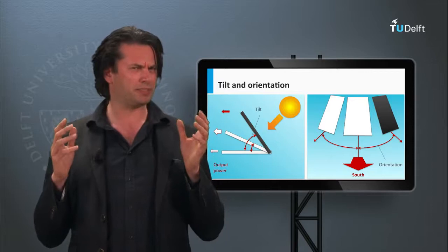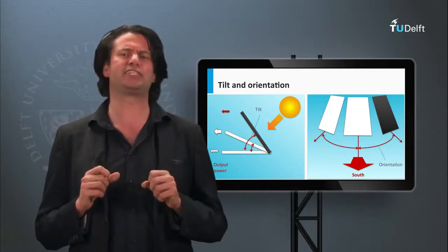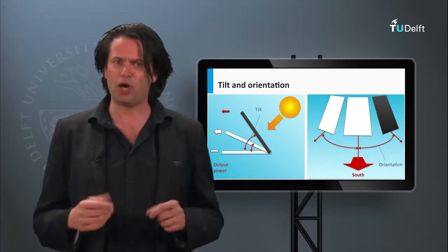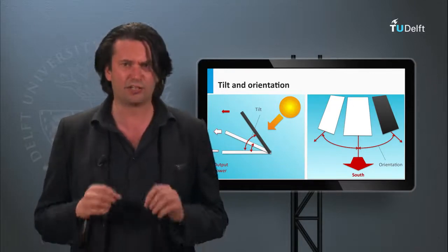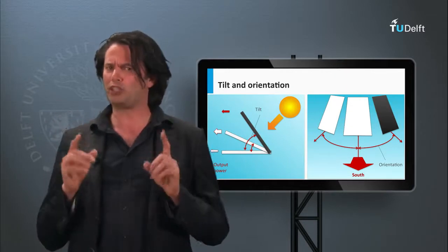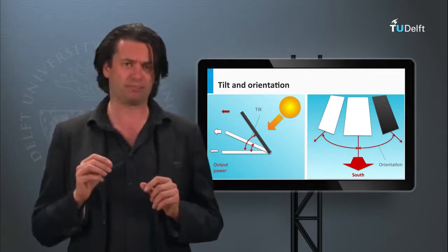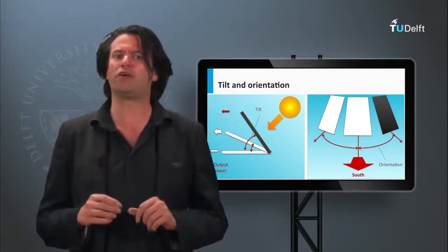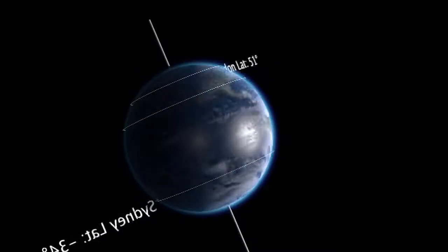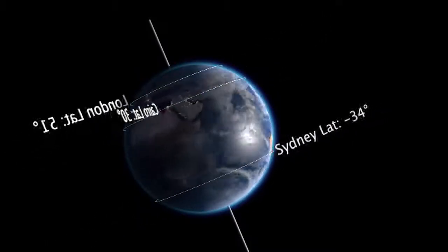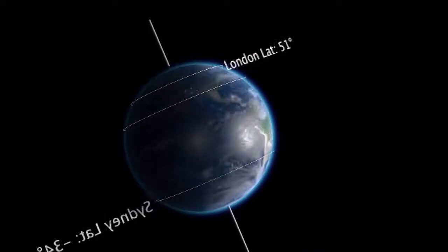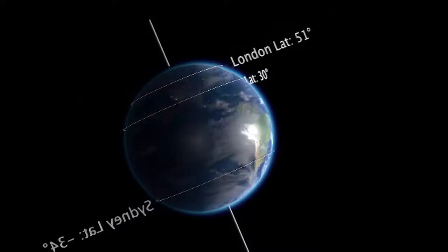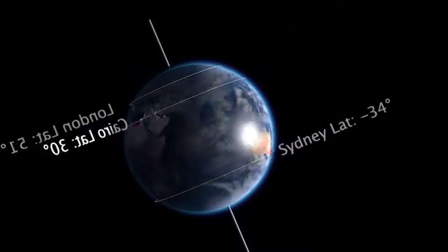What do I mean by this? As the majority of PV systems have fixed mounting of panels, designers have to live with a single orientation and tilt throughout the year. So what should these fixed angles be? The answer would change depending on the geographical location. Here we see various places marked along with their latitudes on the globe. Depending on the latitude of the place, a panel tracking the Sun will have to go through a range of tilt angles throughout the year.